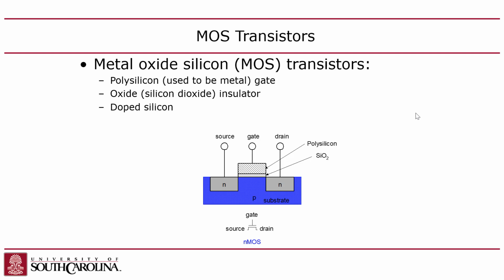And okay, so anyway, what's the purpose of all this? Well, here's the part that's crazy. If you put a positive voltage on the gate, the gate and the substrate are a capacitor. I mentioned there's also a capacitor between the diffusion and the substrate, but there's also another capacitor between the gate and substrate, because there's two conductors separated by a non-conductor, an insulator.